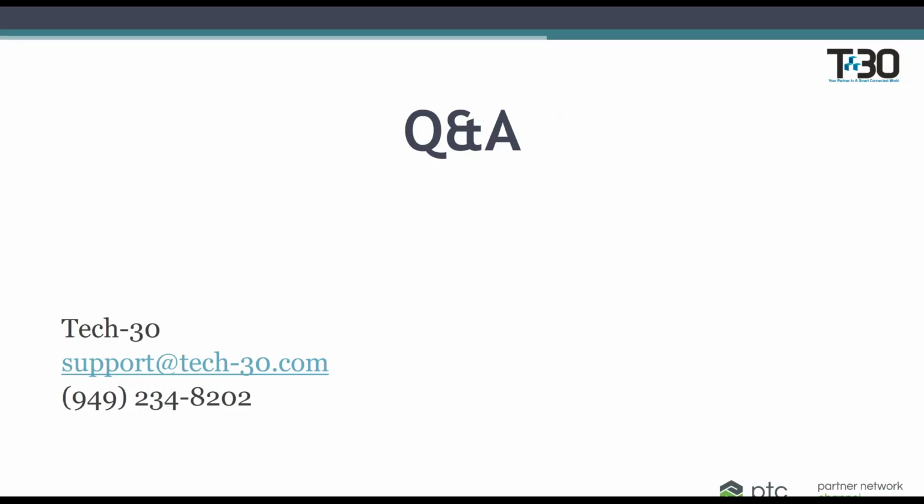Thank you. So another question, we only got a couple more. Does Creo 4 support the STEP AP242 standard? Yes, that's a new standard, and we support that in Creo 4. Okay, wonderful. And what standards is the GD&T advisory using? My understanding is this is more related to the model-based design extension of 3D models with GD&T. Yes, that's a new extension in Creo 4, and again, we've updated our standards, so that supports the standards for ASME Y14.5 as well as ISO 1101.